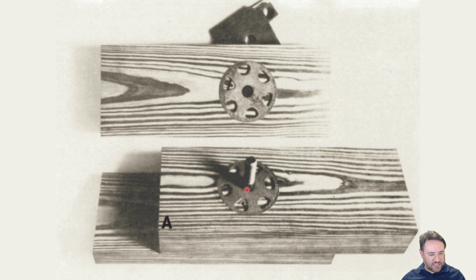Now, in this case, the bolt does double duty. It doesn't have to keep the rings in place, but what it does do is provide the shear. And what this does is it makes sure that the mechanism for failure is now going to be the shear yielding of the bolt.